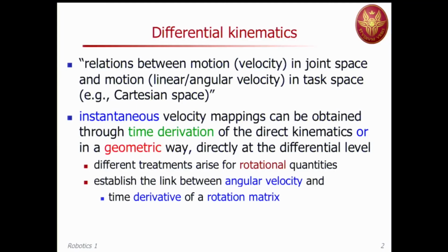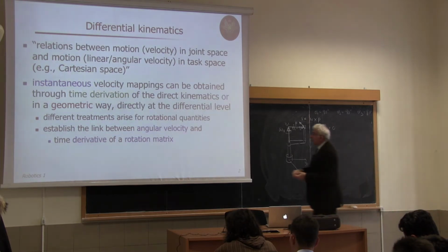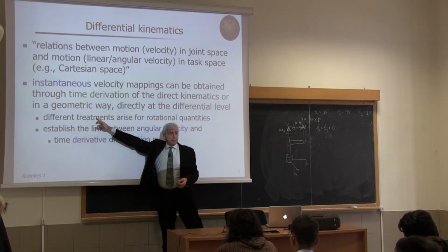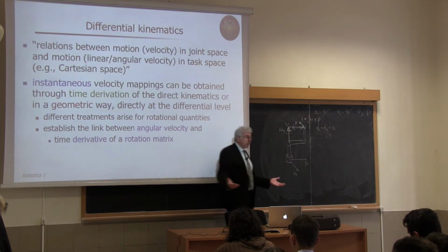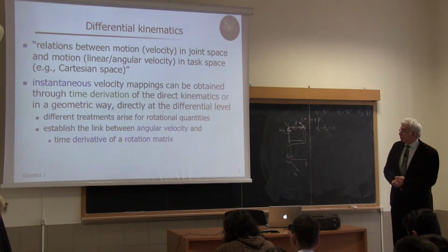So, for instance, we need to establish the link between the angular velocity of the end effector, and in general of a rigid body, which is a vector, so it's a geometric entity, and something that we may derive by time differentiation of angular orientation.